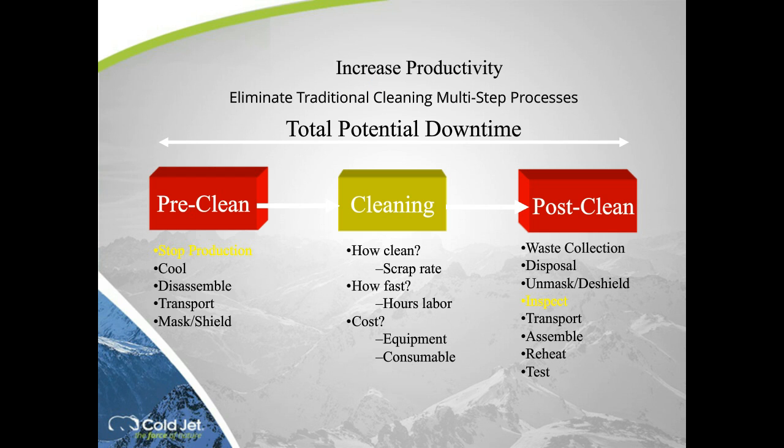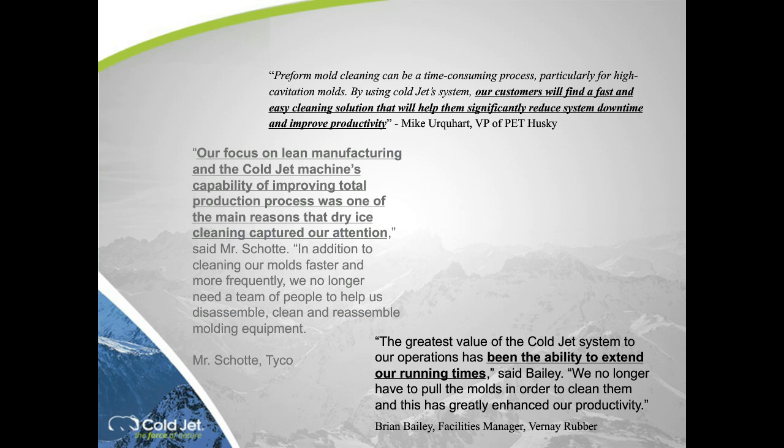This is why a lot of times cleaning is time consuming. It's a multi-step process, particularly if your molds are heated in any form. You go through this multi-step of pre-cleaning, all the sub-steps, the clean itself, then you've got the post-clean, including possibly reassembling and reheating things. We need to stop the production, inspect, and move on. All those other multiple steps that are listed can be eliminated cleaning with dry ice. It just makes it faster and easier to do.